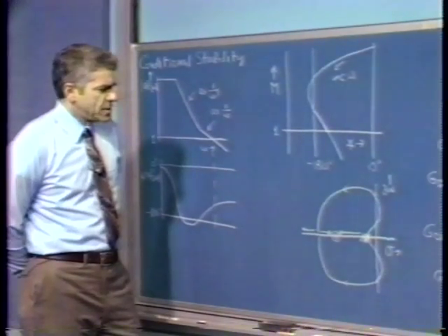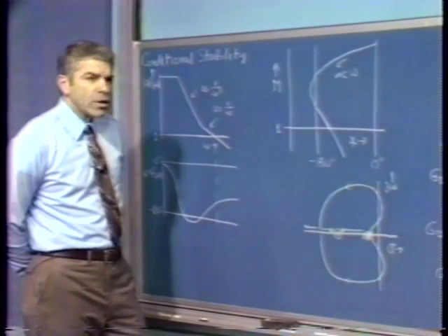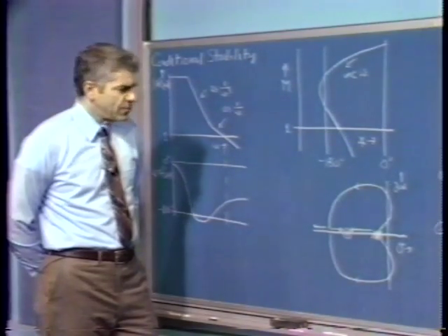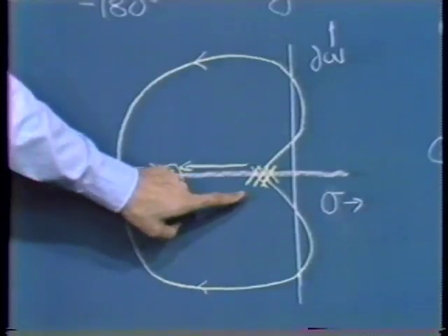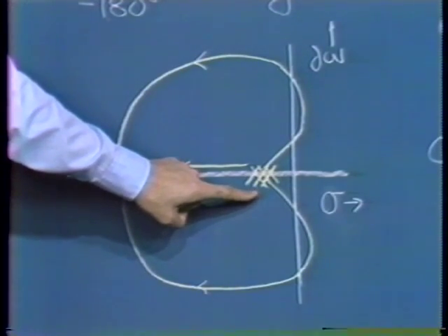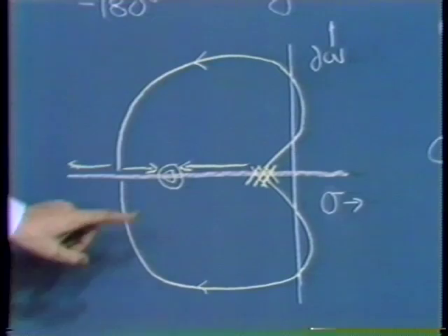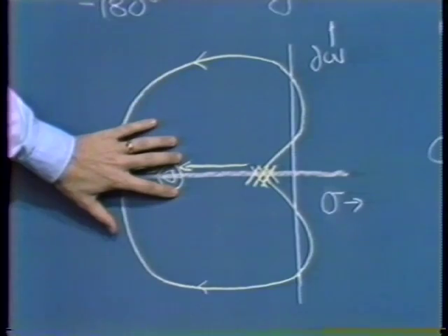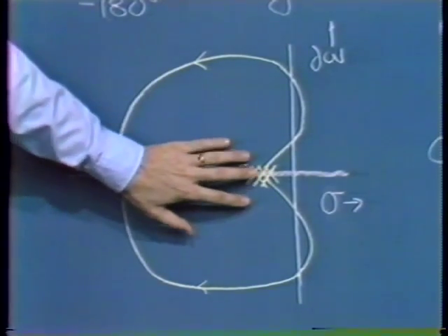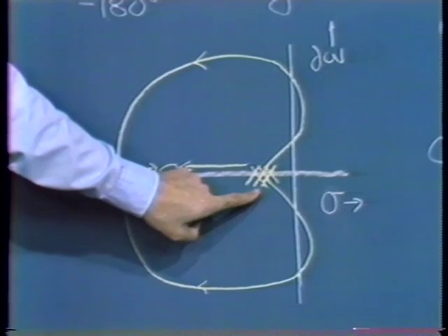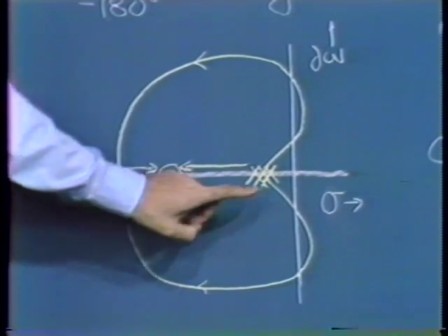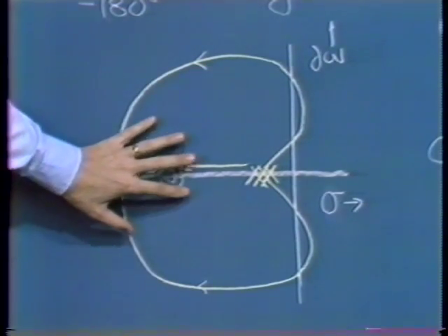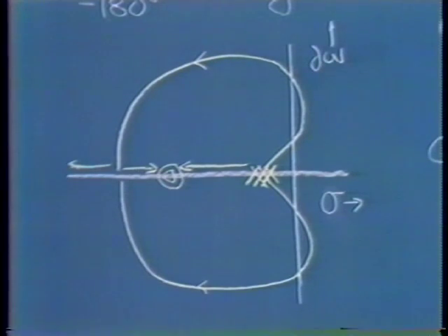We can look at the system in one more representation, and as we go through the analysis, I'm going to try to play these various techniques off against each other so we can see the interrelationship among them. We said that the system has 3 coincident low-frequency poles and 2 higher frequency zeros. Providing there's enough separation between the frequency at which these 3 poles are located and the frequency at which these 2 zeros are located, the root locus diagram for the system will look as shown.